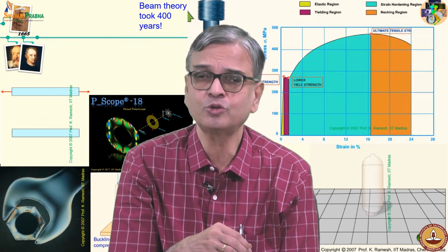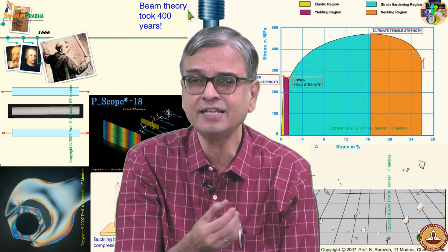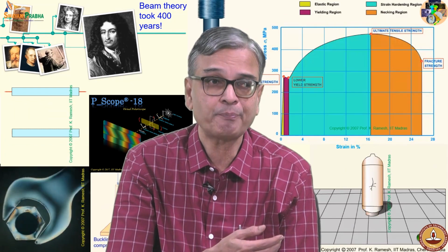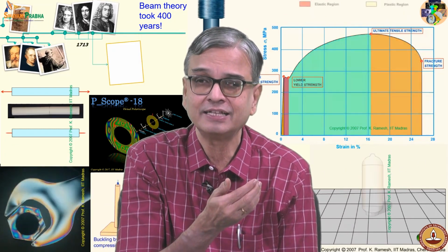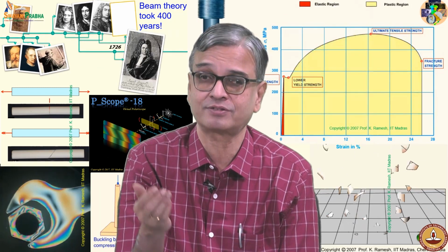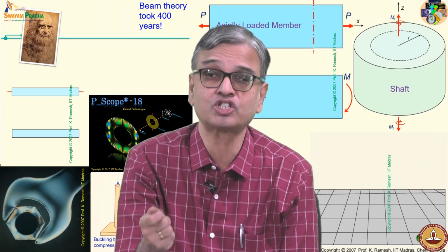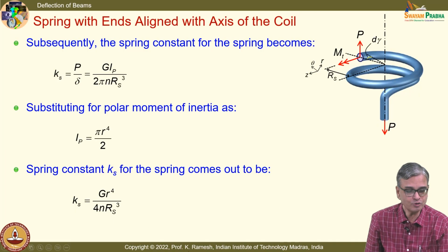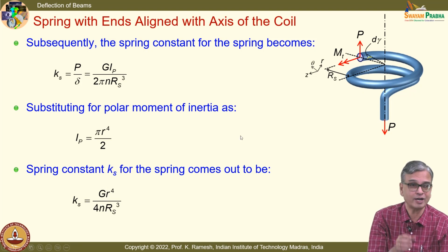But the moment I come to a spring, I get this diameter of the wire by an extrusion process. By processing the material, the number of defects are reduced. A thin wire is much stronger than the bulk material. So if you go to spring design, they will not use the bulk material properties to get the G. They will test for this diameter of the wire. You have procedures available. These values will be higher than the bulk material values because it has fewer defects.